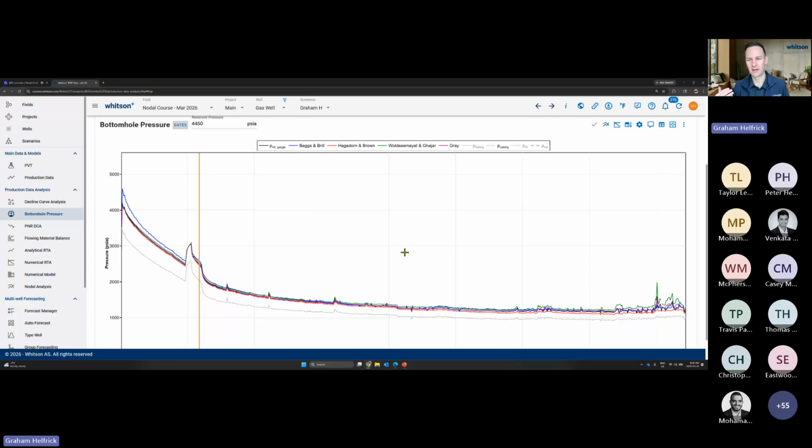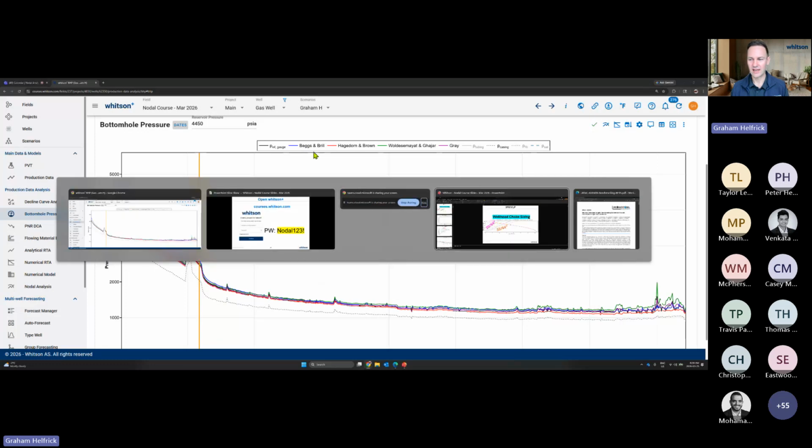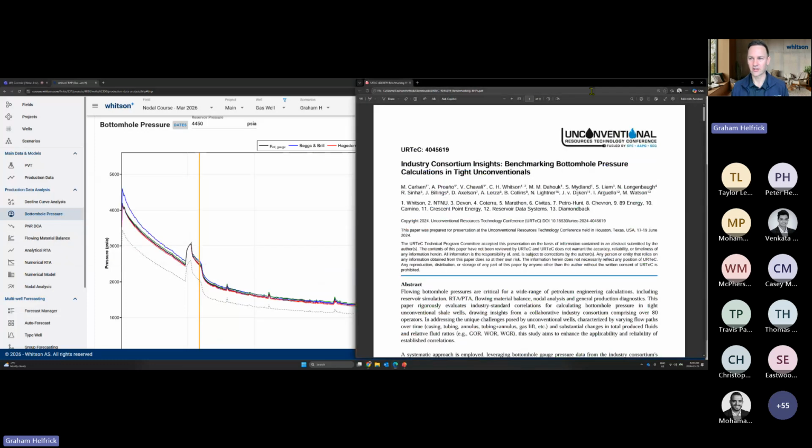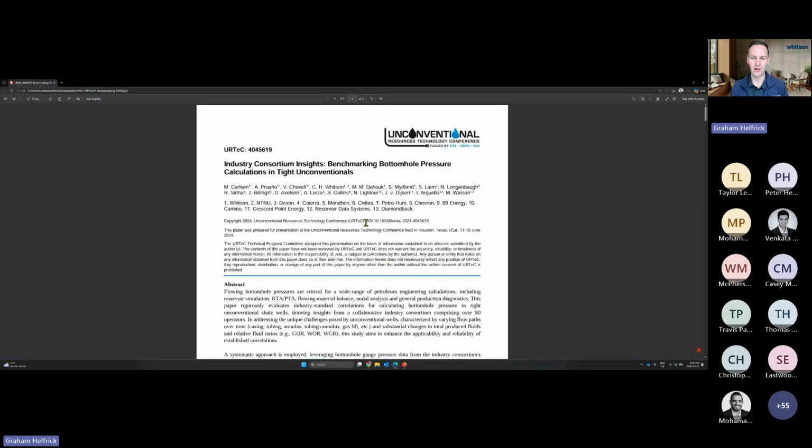So you're thinking, okay, which correlation do I use? I was taught that Gray is good for gas wells, Hagedorn and Brown is good for oil wells, and Beggs and Brill is good for wells with water and hydrocarbons. So is that true? Well, two years ago, we did a study to answer that question. And I'll send you guys the paper in the follow-up.